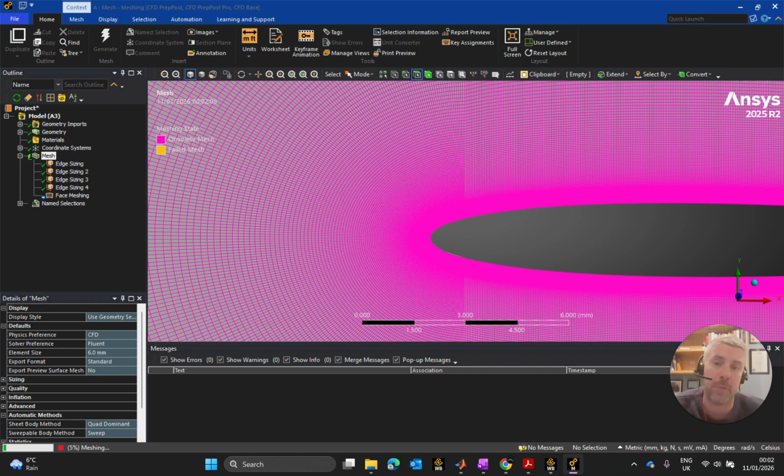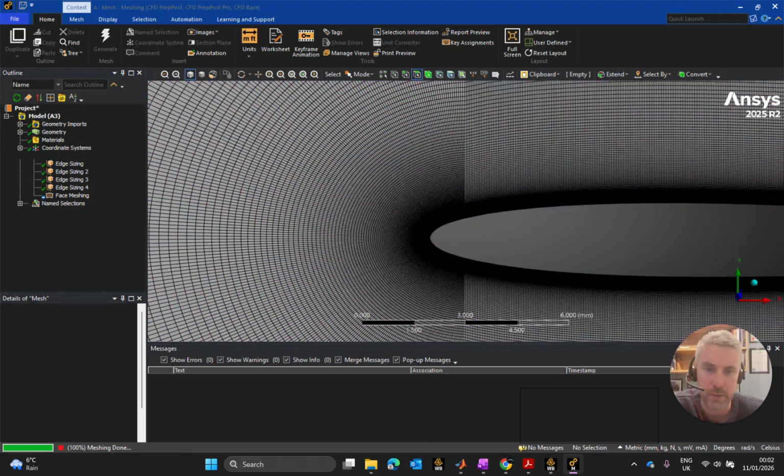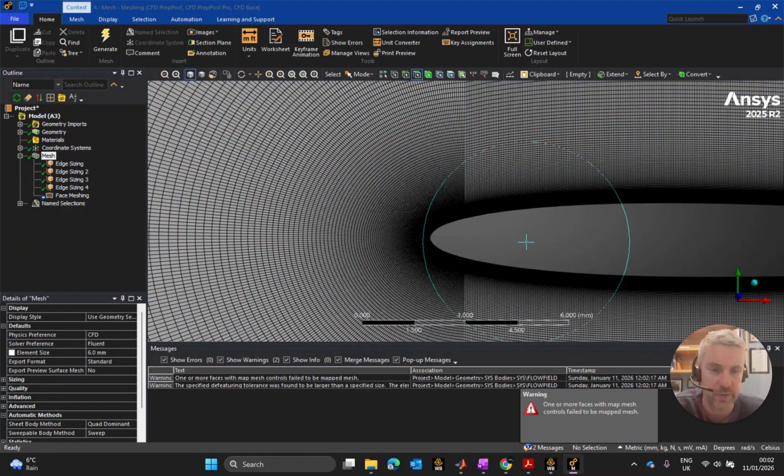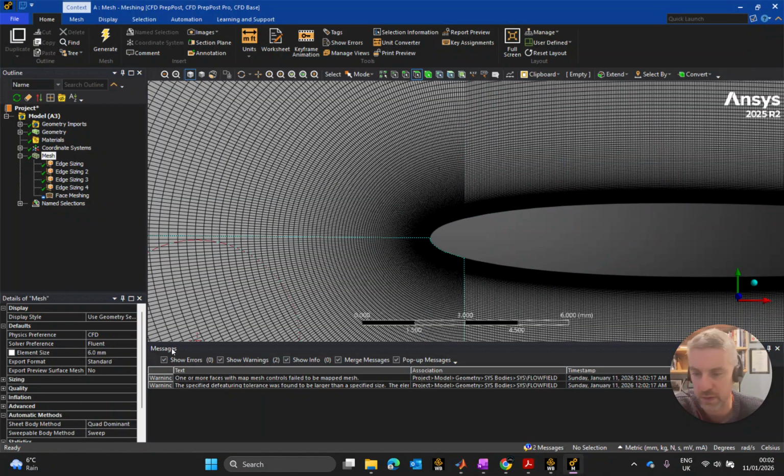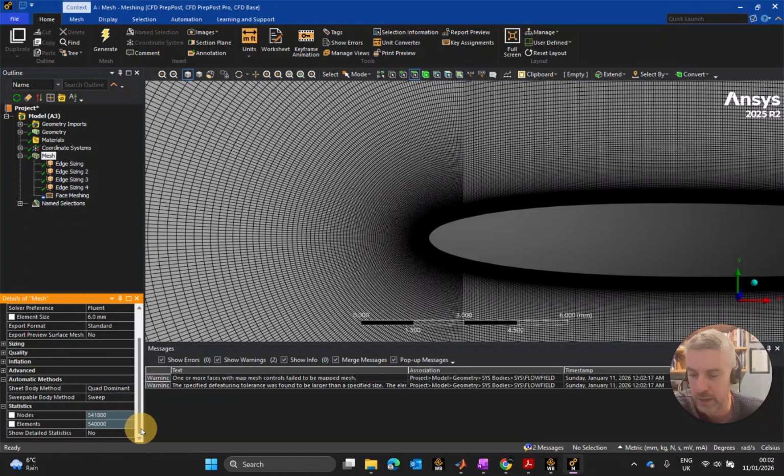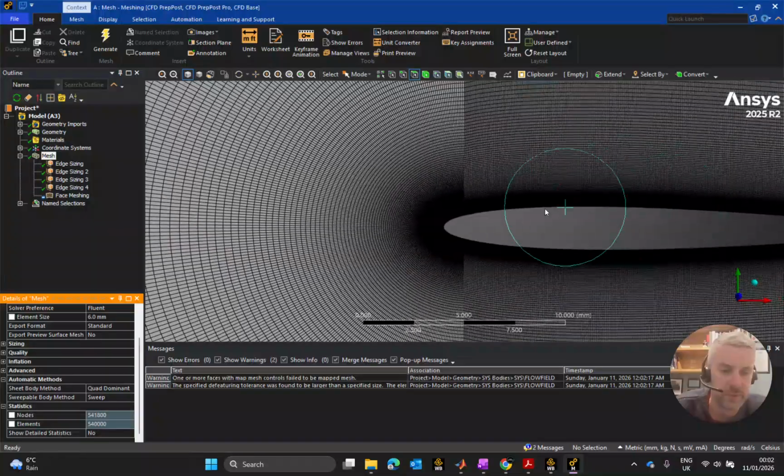So as I said, 3 out of the 5 days of meshing, if you're spending a week, a lot of it is doing this. Now I'm probably going in a wee bit heavy on it just now. Probably don't need to go to this level at this minute until I get into mesh independence. But that said, there and back down into the 500s, still heavy enough.